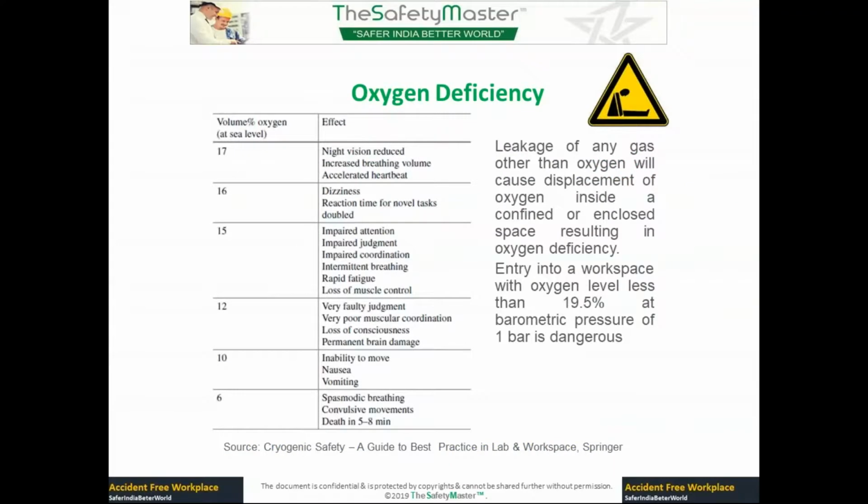Now coming to the main hazards related to all these gases, one is oxygen deficiency. Okay, now let me cover it as early as possible because we are running short of time. One is the volume of oxygen. The moment it is below 19.5, this you should always remember. Normally in air you have 21% oxygen, right? So the moment it drops below 19.5, then it is hazardous. Okay, so always keep that in mind.